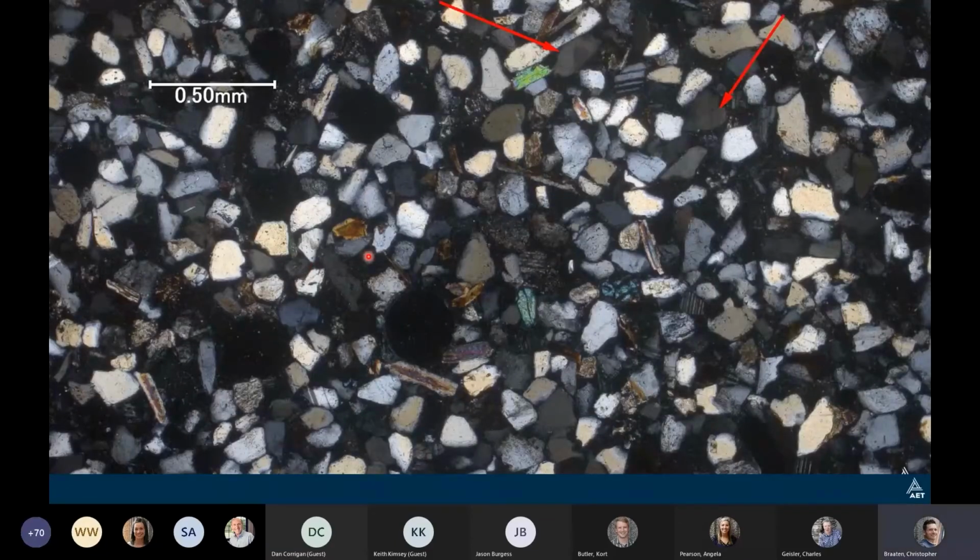This is the thin section picture of the number 200 sieve. So like coarse aggregate, on fine aggregate, we also run a gradation. We take the gradation and we do a hand sample lithological count on the number 4 sieve and the number 8 sieve, because we can see those pretty well under our stereo zoom microscopes. Anything below that, number 16 sieve, 30, 50, 100, 200, and the pan, we make epoxy plugs. So we put it in a little boat and we fill it with epoxy, let that harden up, and then we can put it on a thin section slide and make a nice slide.